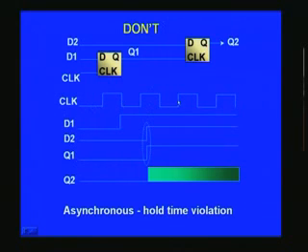So, for example, this is the clock, and D1, D2 are coming from an external source, and suppose D1 changes somewhere here, arbitrarily we choose here, and D2 changes here, and simultaneously let us say this Q1 also changes. This is possible because D2 is not in our control, so it may appear at any point of time. So what prevents you from getting that D2 change when there's a rising edge for this clock? You can't. So in such an event, you are actually violating the hold time.